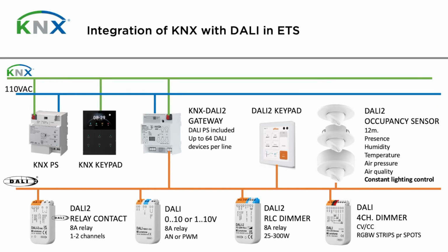For a DALI ecosystem, is there any programming software like ETS? Yes. On the Lunatone website, you can see a tool to program and to assign DALI IDs, because in DALI every ECG, every device, has an ID. The first thing you need to do during commissioning is to assign a DALI ID to every single ECG.